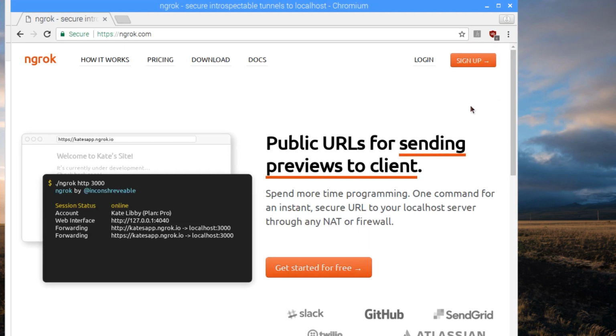So what Ngrok does for us is that it allows us to expose a publicly available URL from our Raspberry Pi. When we configure our Alexa skill, we'll be running a Python skill handler program on our Pi, and in order to access this, it has to be made publicly available via an HTTPS URL.